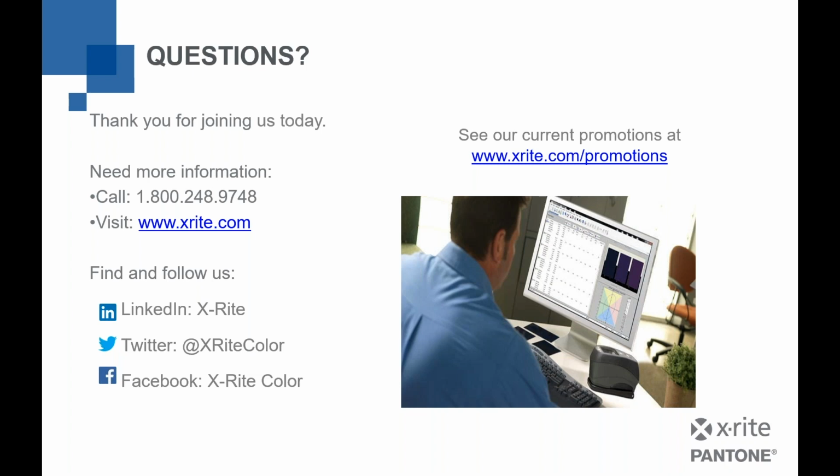Generally, in the paint realm, in most ink films, you're going to use a coated contrast ratio card, so the pigment and the resin is not absorbing into the card. It's sitting on top of the coating. That way you're very consistent in what you're doing. But like I said, we can help look at your process and help you specify exactly what type of substrate you need. We'll take a few more questions.